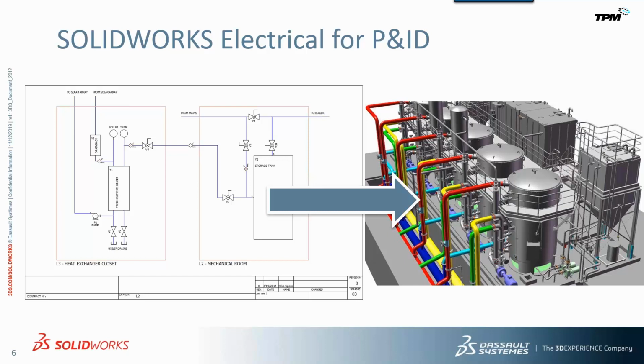The 2D program is on the left. It is really 2D. It is schematics. It is 2D symbols, lines, arcs, that kind of thing. But make no mistake, that ties right into SOLIDWORKS 3D Mechanical, where we will actually route those 3D pipes in space, give them nice color schemes for hot water, cold water, returns, whatever it may be. And you can see just the graphical representation and the impact that that has.